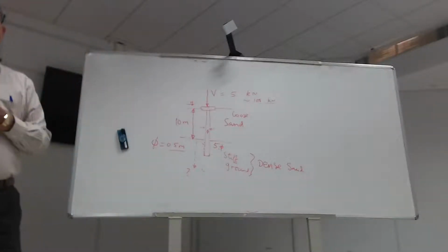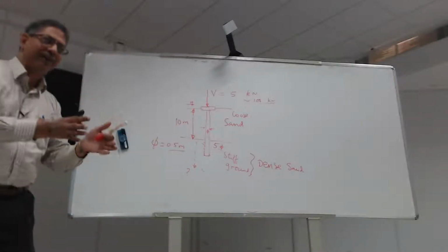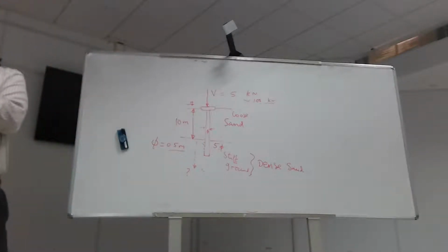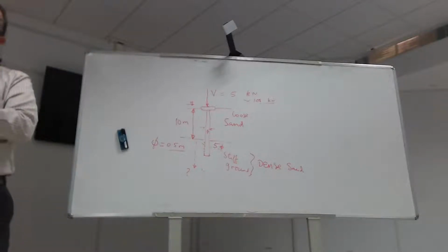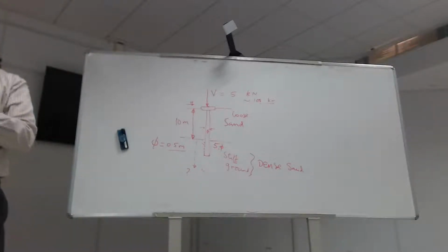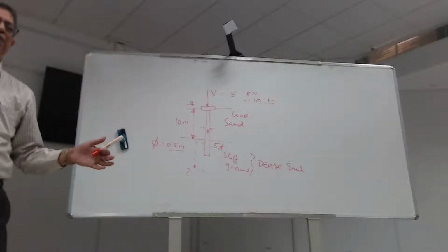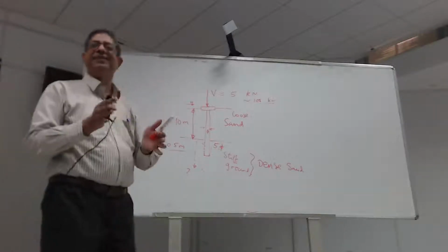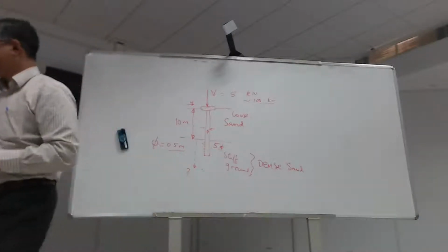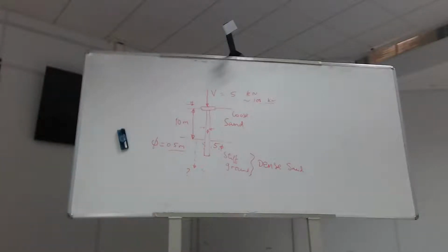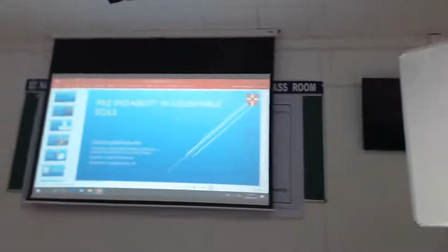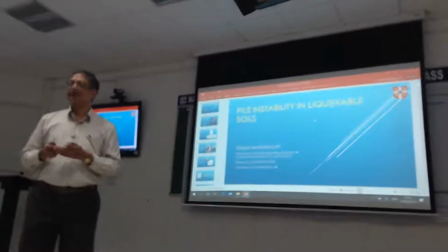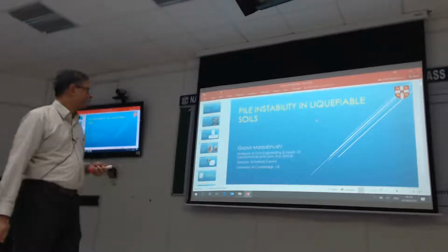So you've got a situation where you start solid, you turn into something like a semi-liquid, and then if you leave it long enough, it'll again become solid. So before the earthquake, few minutes after the earthquake, you have no problem. However, what matters is the stuff in between, and that's what we'll be looking at. So we want to look at the instability of these piles under this very short time frame from the life of structure point of view, but it's quite important from an earthquake perspective.